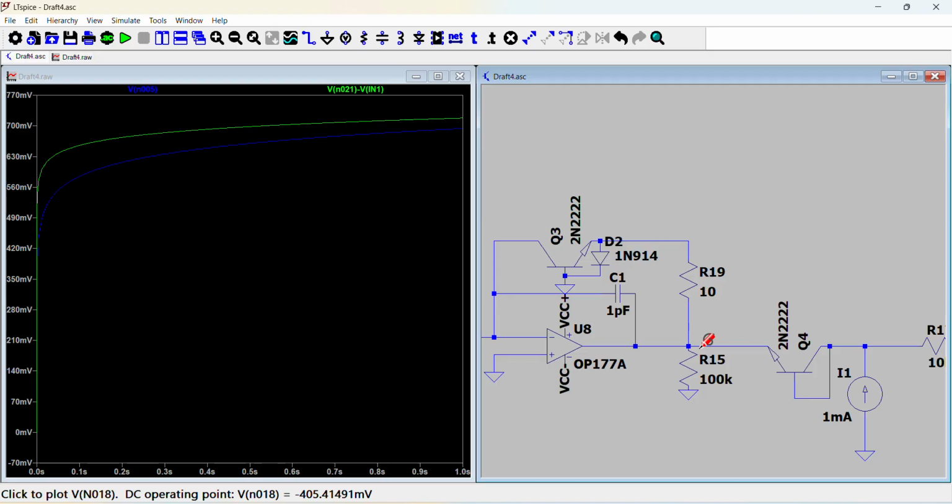And because of that, what happens is op-amps have an inherent problem with stability if your feedback factor is extremely high. Because when it's extremely high, the gain bandwidth product, which is how much the op-amp can amplify signals at various frequencies, at very high frequencies, does not drop below 1 when it's multiplied by the feedback factor.